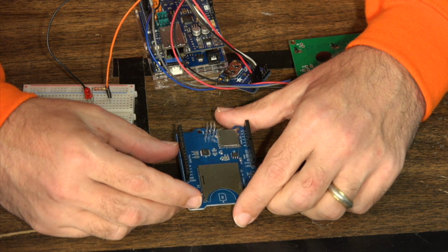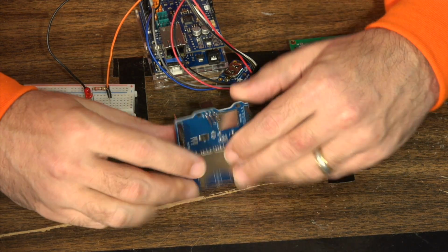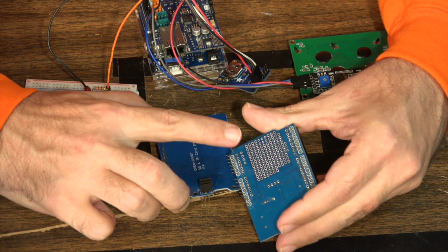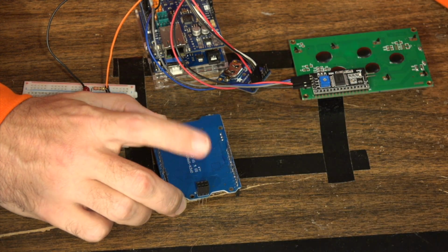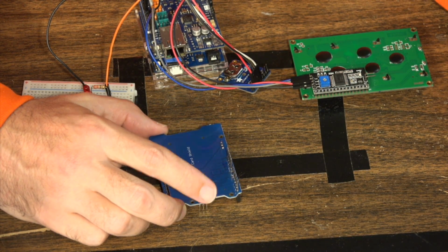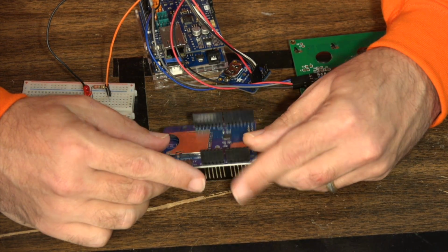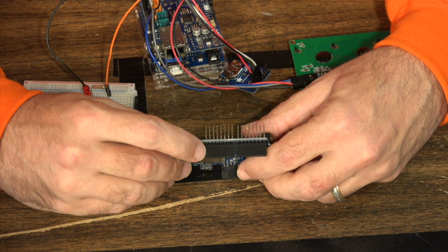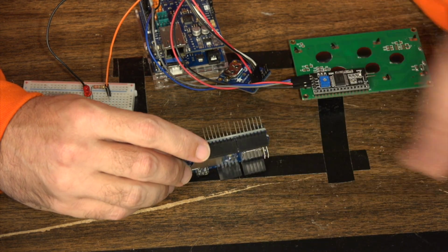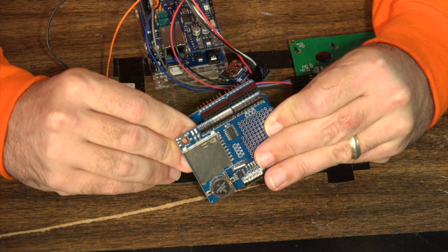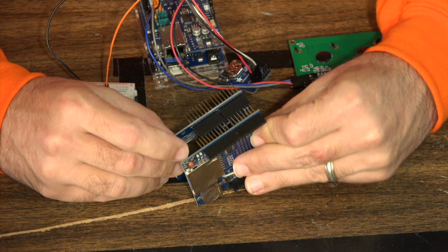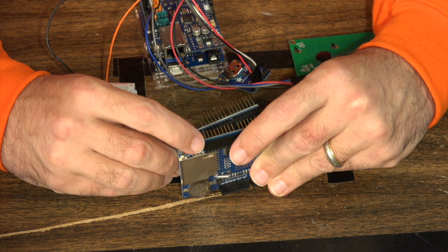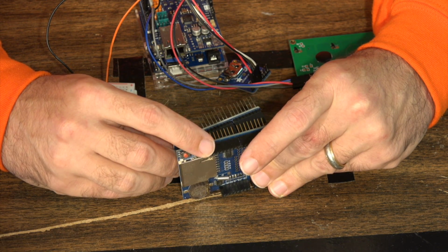This data logging shield I actually specifically bought because it has the ICSP headers, right? See, no ICSP, yes, ICSP. So this actually does have the ICSP headers, but of course, what it does not have is the SCL SDA pins that go all the way through on the bottom. So you can even see here, with this particular shield that doesn't have the ICSP headers, it does have the SDA SCL that goes all the way through.